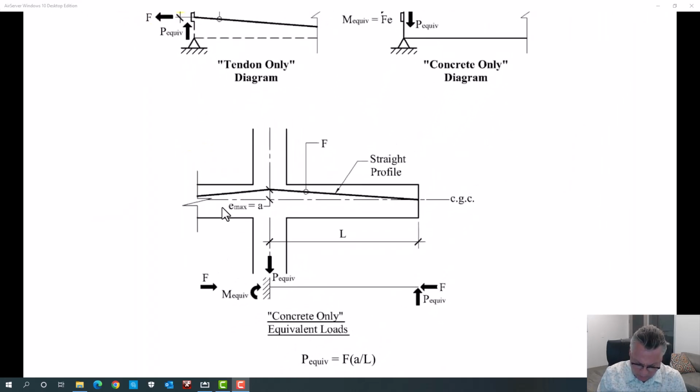So that leaves us with cantilevers. And I really like cantilevers. I like them for many reasons. Mainly because we in post-tension concrete can do them easier than anybody else can. In wood, cantilever is a tough thing to do unless you place a beam over a post. You can cantilever it that way, but that's good for about one level.